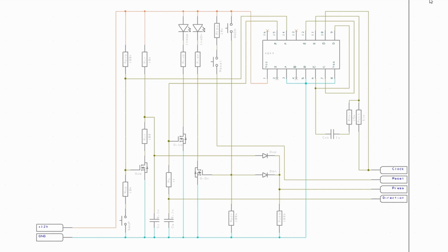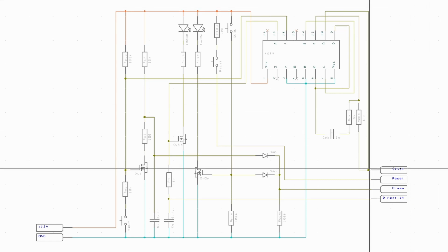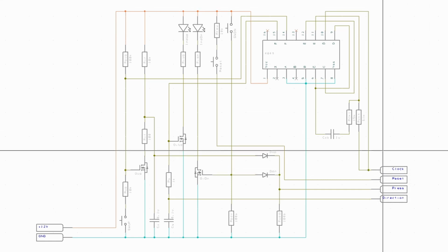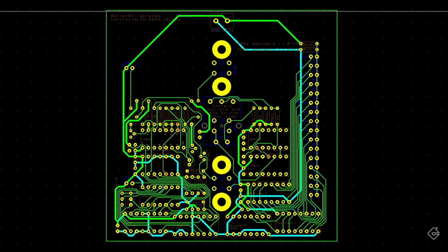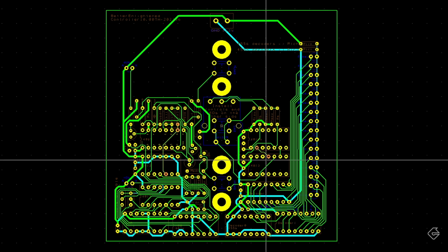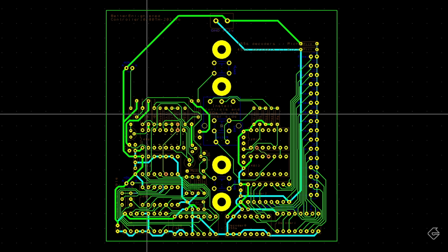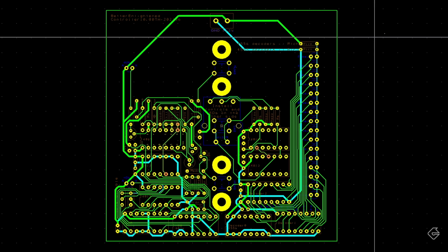Looking back at our button schematic, let's start by highlighting the clock net, and you'll see this gap that I'm talking about. There it is. You see the flashing nets on the board. These are both clock nets, but they're disconnected. The clock net on the right is for our rotary encoder, and the clock net on the left is for our buttons. But the nets must be connected for this circuit to work. So we've got to run an additional trace to make sure that these nets are connected.